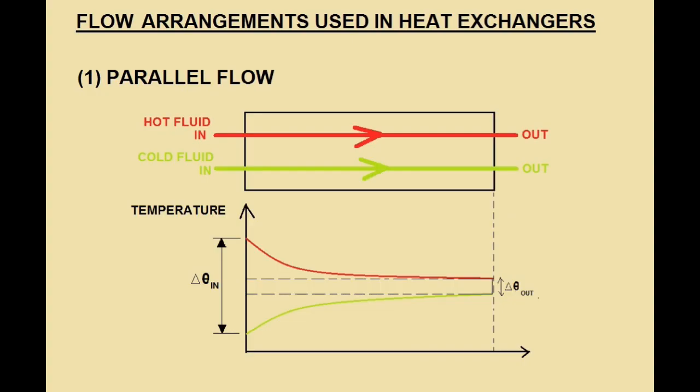Parallel flow arrangement. In the parallel flow arrangement, the hot and cold fluids enter at the same end, flow in the same direction, and leave at the same end. This type is not normally used in marine practice. Two major drawbacks are there in this arrangement.